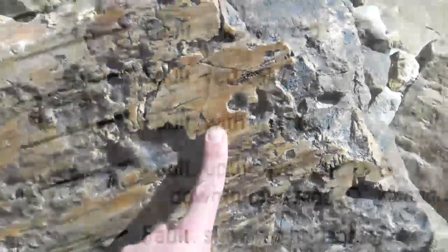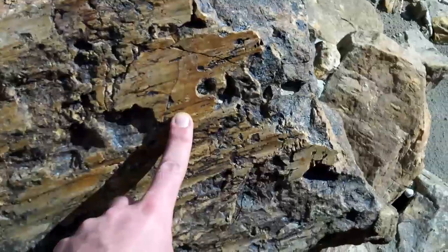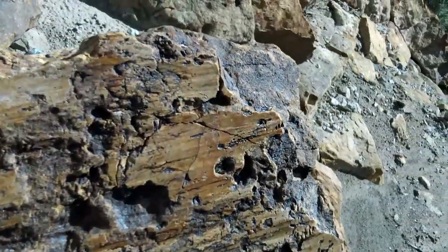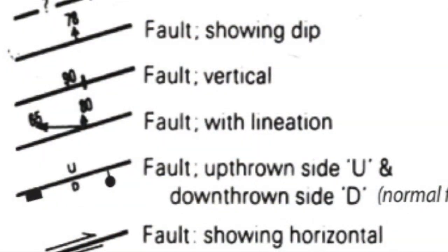Faults often have slickensides, which are a lineation that may be at an angle to the dip direction, and such lineations can be represented with a short arrow perpendicular to the line for the dip direction, and a longer arrow for the lineation, which we'll talk about measuring lineations in a moment. So we use separate dip numbers, as lineations not parallel to dip will always have a smaller dip angle than the true dip of the plane.